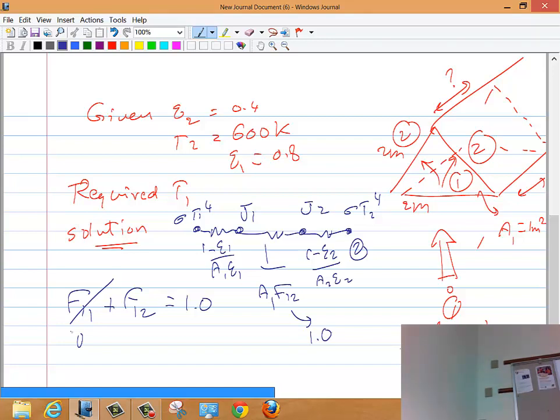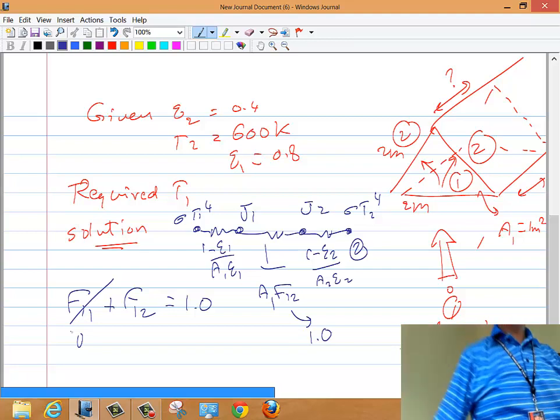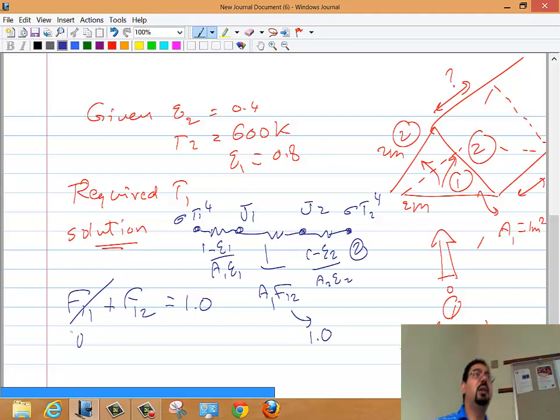Let's imagine we have a roof like the example we solved before. If we have a roof and 2 and 2 are identical, same epsilon, same temperature, I can still look at those two walls that are away from each other, and I would think this is surface 2. So surface 2 does not have to be connected to itself, as long as it's the same temperature and same epsilon. Let alone if you think that surface 2 needs to always be a flat surface, no, it does not have to be a flat surface.